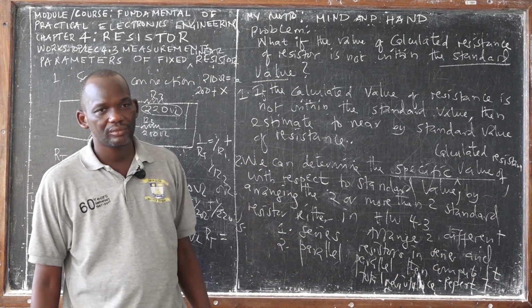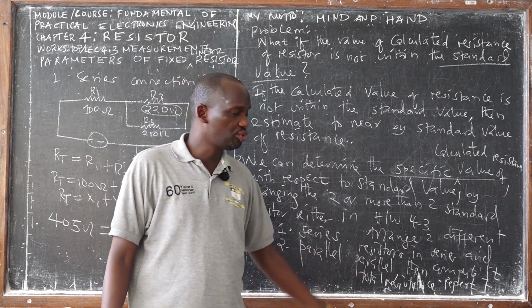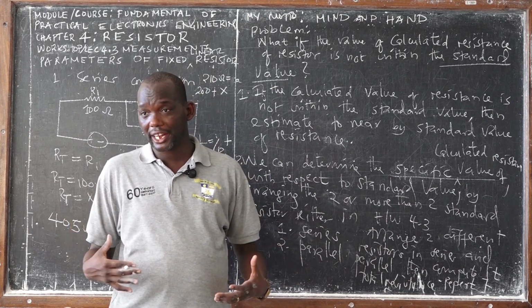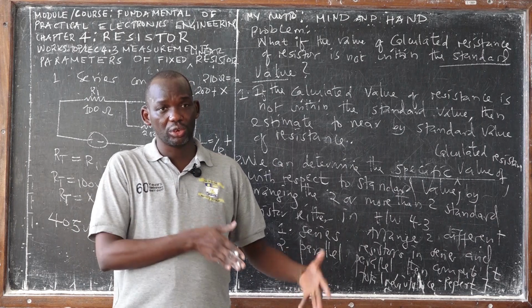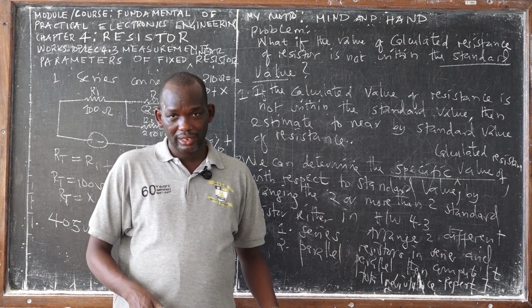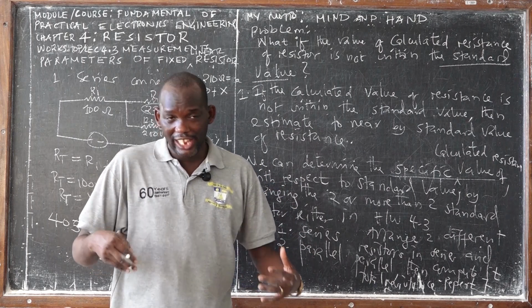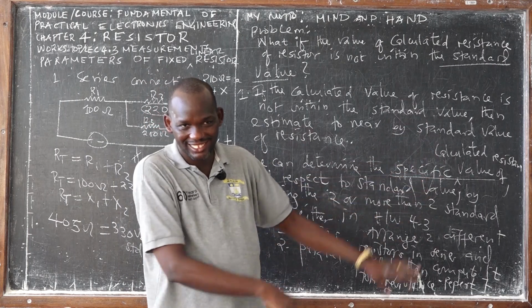What does it mean? Listen, the homework is simple. Just choose any two different standard resistors, connect them in series and parallel, then calculate the total resistance in series and the total resistance in parallel. That will be the first experiment, or the first task. Then do it seven times with other different pairs of resistors.